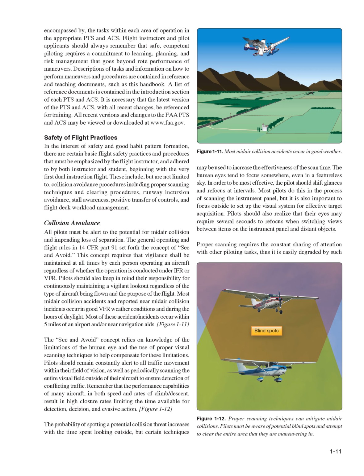Pilots should remain constantly alert to all traffic movement within their field of vision, as well as periodically scanning the entire visual field outside of their aircraft to ensure detection of conflicting traffic. Remember that the performance capabilities of many aircraft, in both speed and rates of climb/descent, result in high closure rates limiting the time available for detection, decision, and evasive action.